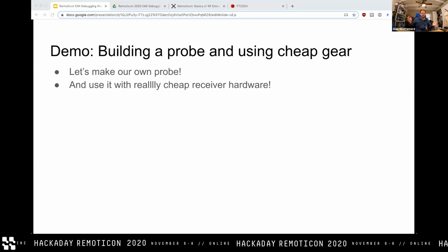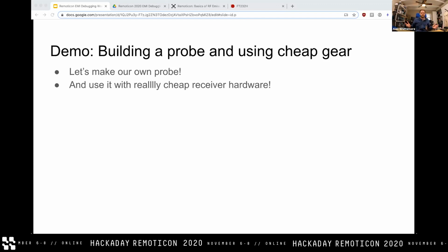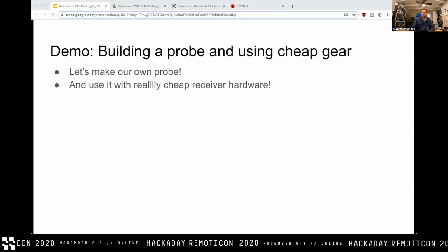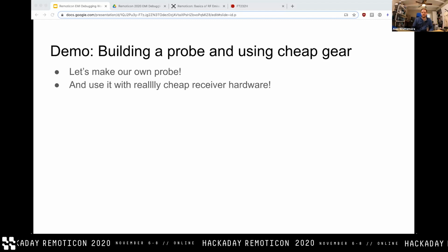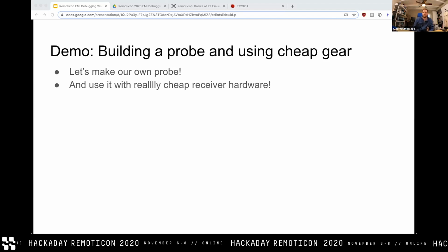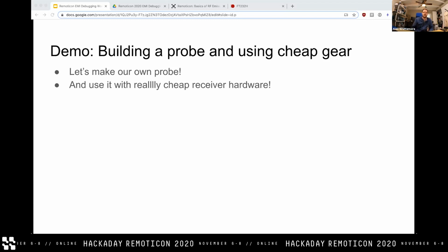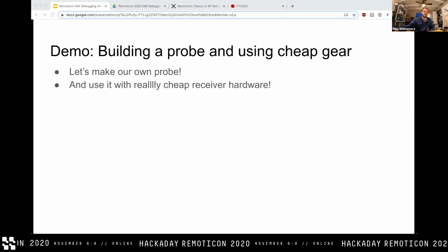It turns out the Ethernet subsystem on that chip operates at 250 megahertz, and there are a bunch of different analog voltage rails and conditioning pins where 250 megahertz is coupled very strongly onto them. So if you have large loop areas and long traces and decoupling capacitors that are not super adjacent to the pins and that sort of thing, that's what you end up with.